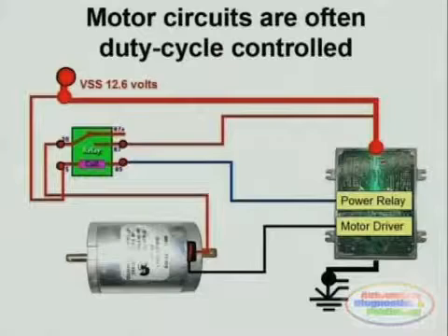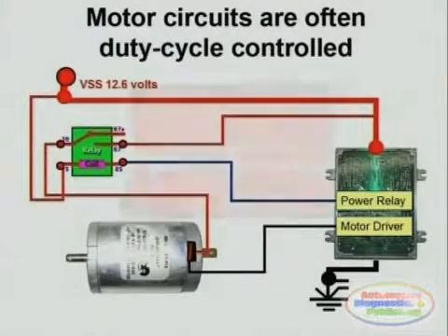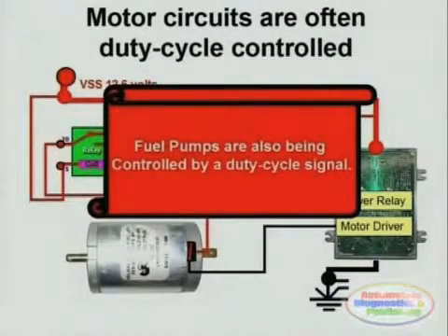This doesn't mean that the motor is controlled by the relay. Fuel pumps are also controlled by duty cycle signals through the negative side of the circuit. The relay provides the positive side to the motor, and the ECM driver provides a pulsated ground to the negative side of the motor.